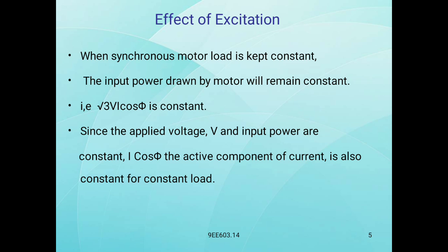Since the applied voltage V and input power are constant, I cos phi, the active component of current, is also constant for constant load. If the load is varying, I cos phi also varies.